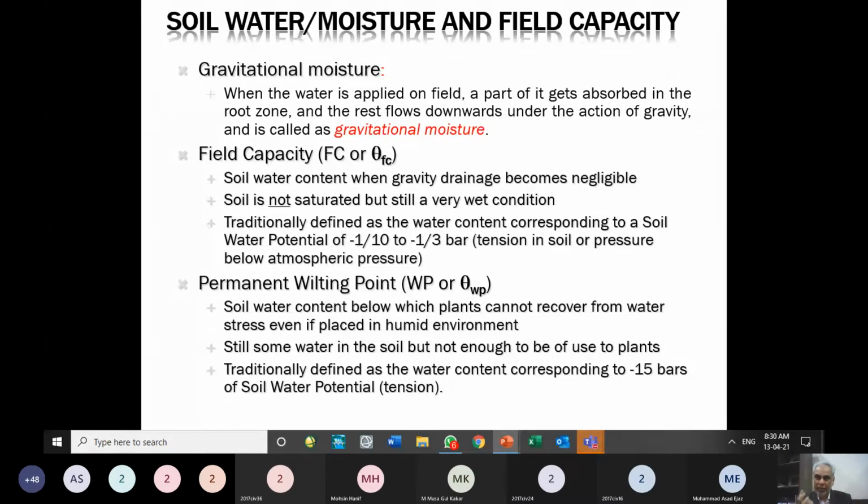When soil gets dry, when it goes towards field capacity or towards dryness, then it has some tendency to attract water because of the capillary action. That tension is called soil tension, and we have a tensiometer available which can measure this lack of pressure or this lower pressure, if we want to measure the soil moisture tension within the soil.